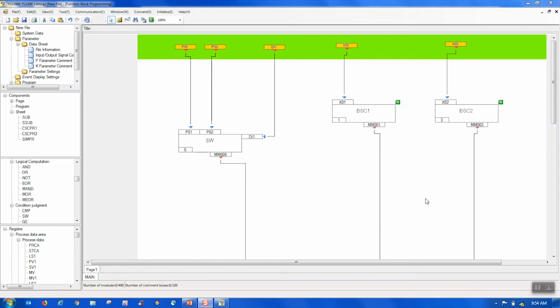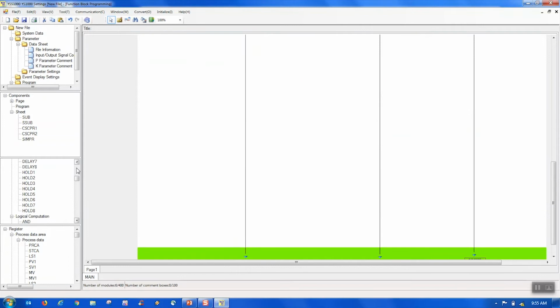Okay, continuing with the control loop here. For example, on the second loop, I may have a control output that normally we have a 4 to 20 milliamp output. Maybe I want to reverse that and have 20 milliamps to 4 milliamps. So 20 being your 0% output and 4 being your 100% output. What we need to use is basically a linearizer or a g of x function.